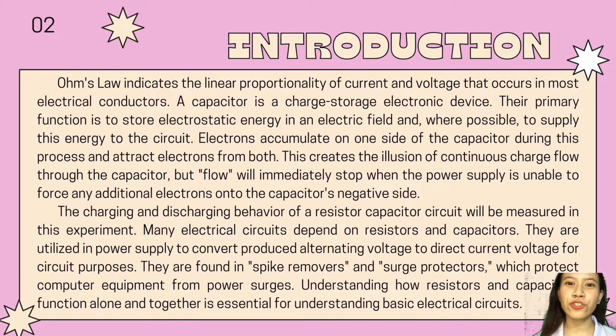This creates the illusion of continuous charge flow through the capacitor, but flow will immediately stop when the power supply is unable to force any additional electrons onto the capacitor's negative side. The charging and discharging behavior of a resistor-capacitor circuit will be measured in this experiment.